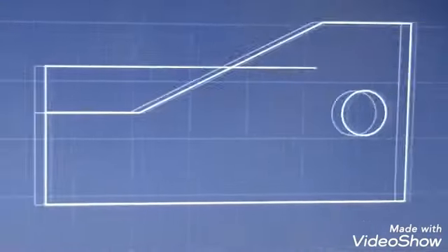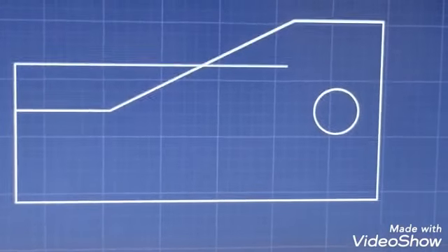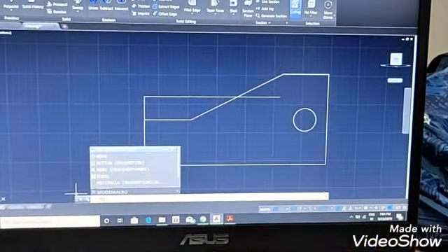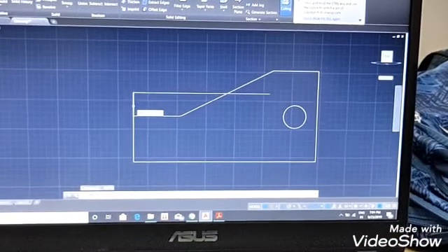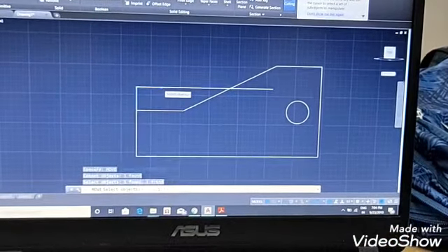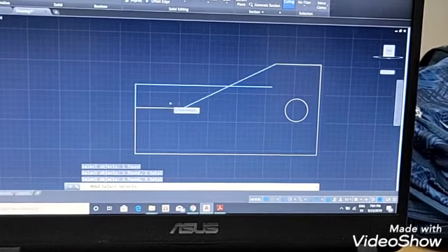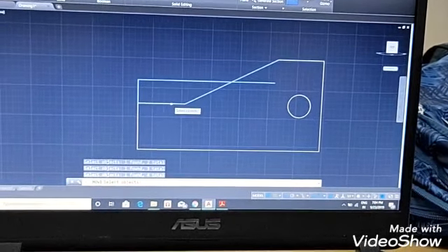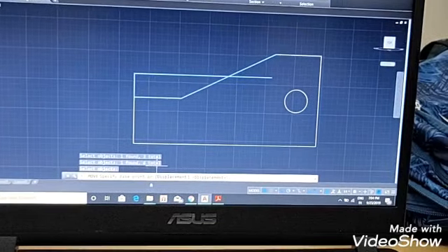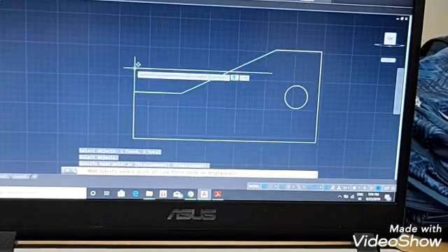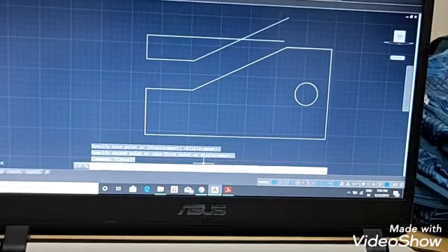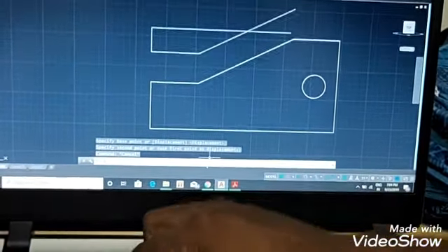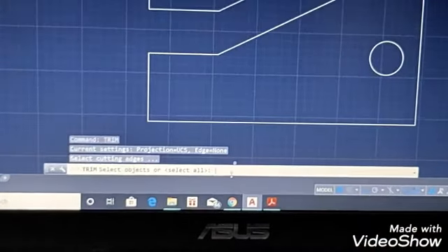Okay, I have just drawn lines over these edges itself. Now I will use a move command to move the drawn lines. Enter. The next it is asking base point, and selecting this as a base point, keeping it some location. Escape. Then use trim command, trim.